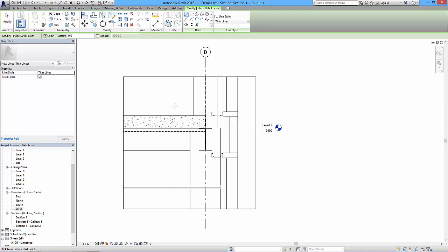So what we're going to do in this tutorial is create some AutoCAD files from AutoCAD, then import them into a detail family, and then bring that detail family into this model environment as a 2D object, and then we can do all sorts of different stuff with it. It is quite a simple process. It's just a question of bringing in and referencing external materials or external drawings, and then putting them into place.